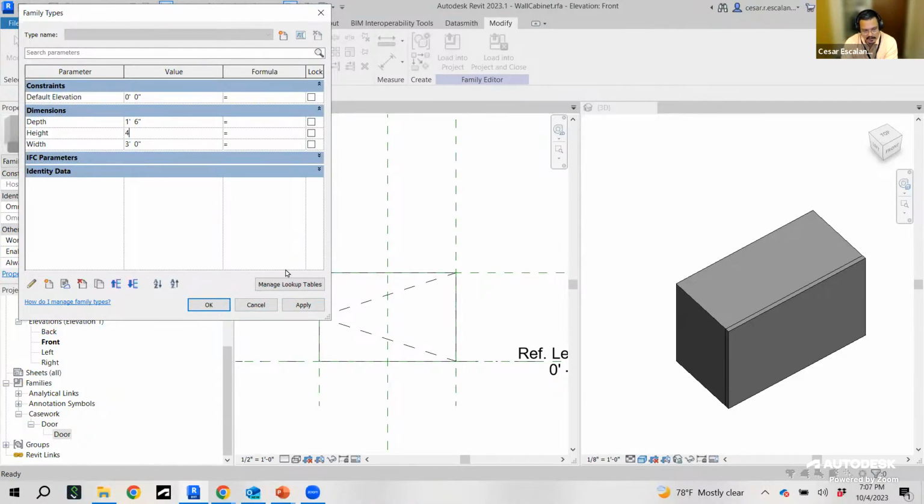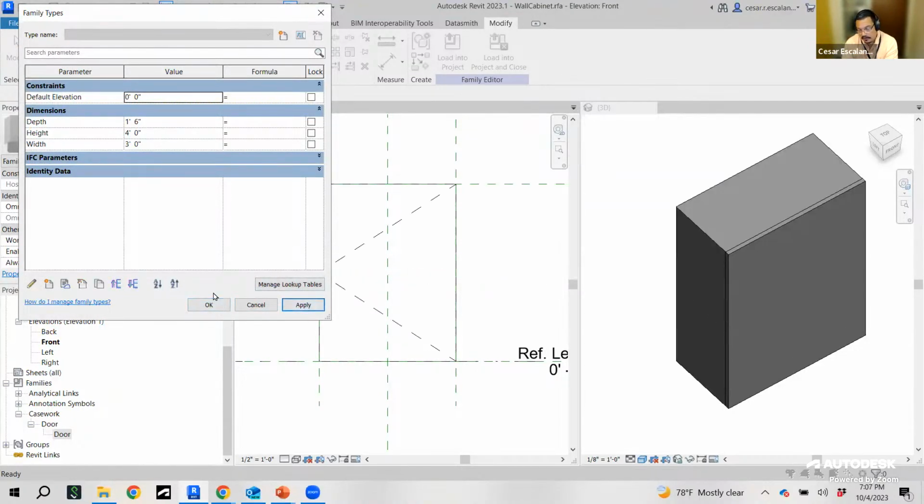a parameter inside another one, and then associating the type values using the associative toggles, is an excellent way to build smart families. You don't have to individually create all these additional parameters to drive the parameters of the door. I mean, the door is a nested family with embedded parameters, and those parameters are connected to the host. You just change the parameter of the host, and then the nested family changes parameter as well.